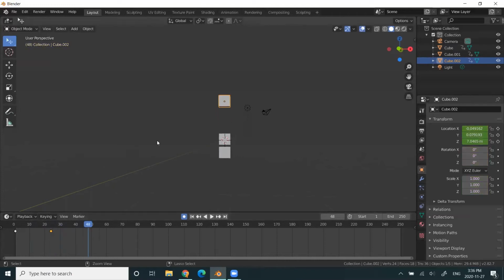So what you want to do is a hold. That's all that means: you have the same keyframe copy and pasted somewhere else along the timeline next to each other. So when this is being pulled apart and I have this object selected at the top, I can just scrub through the timeline. Let's say maybe I want 2 more seconds to hold this pose. That's about 48 frames, so 72 right here, and then I set a key.